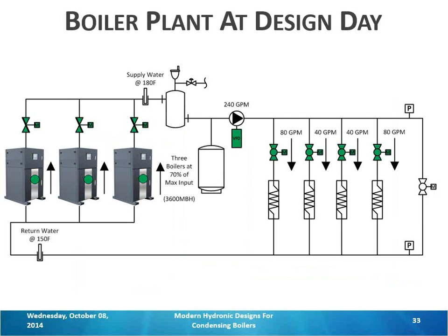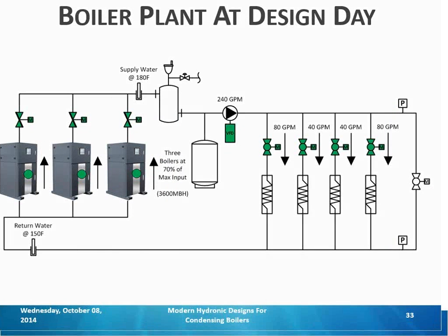But then we turn the system down. The boilers are turned down, the pumps are turned down, the load drops in the zones. And as those valves start to close, they're throttling the system. And our system curve actually shifts a little bit on that pump curve, goes to the left. Just like closing down a throttling valve. But at the same time, we're modulating a VFD down.